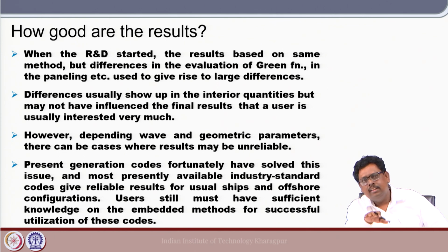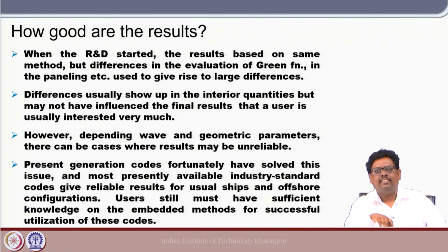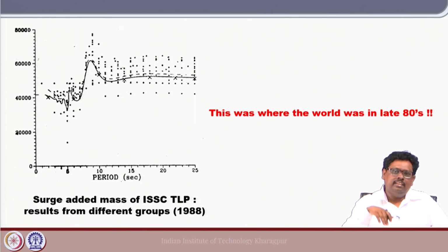So, that is the point. These are fairly complicated software packages. You have to have some domain knowledge to assess your results, to overcome the difficulties, and to know what is good meshing and bad meshing. So, let us not go blindly making the mesh finer to get very good results. It will not work. Okay. Fine.